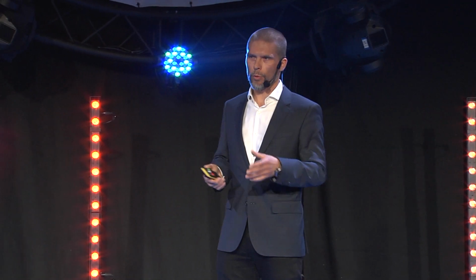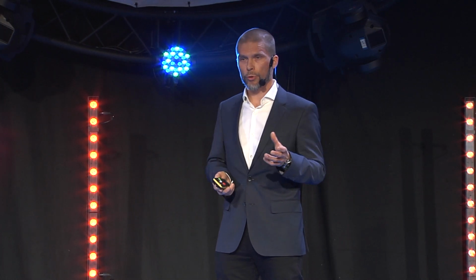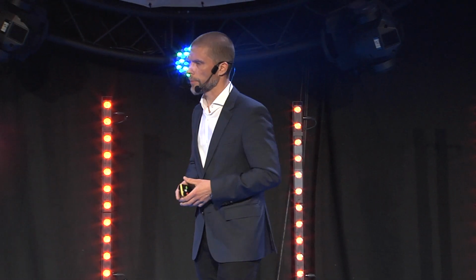If we would target a very high true hit rate ratio, so that we only notify you if there's a real event, that would mean that we will miss a lot of events as well. So the idea that we had is, okay, we're not going to aim at 80 or 90% hit rate, but it should be more than just a couple of percent, which would mean that you would have 100 warnings, only a couple of them are real, and in the end, people just turn off the monitor and do not look at that. So we are typically targeting about 20 to 50% true positive hit ratio over time as we go forward. And that will give good enough warnings, but also lower the risk of missing real events in the factory.